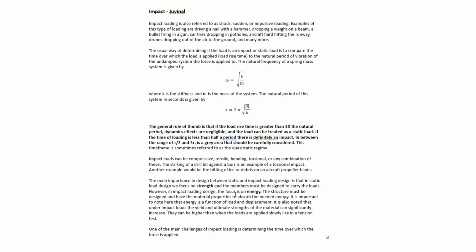One of the main challenges with impact loading is determining this time over which the force is applied. And we'll call that the delta T. And we'll find out that that has a huge impact on the magnitude of the force, and it's also a pretty difficult quantity to determine.